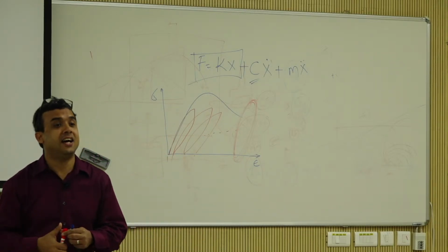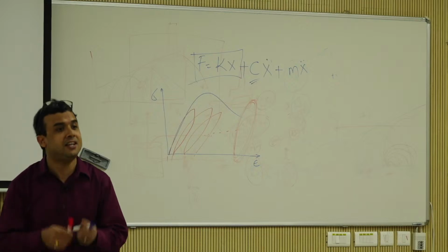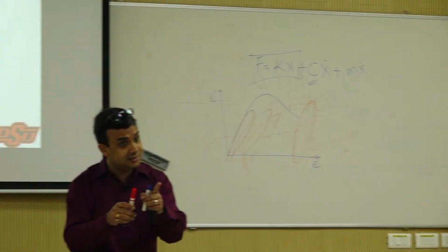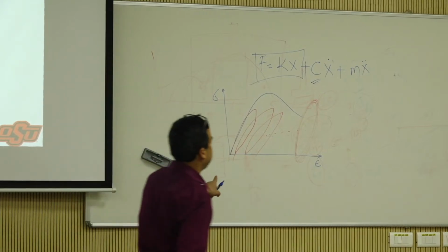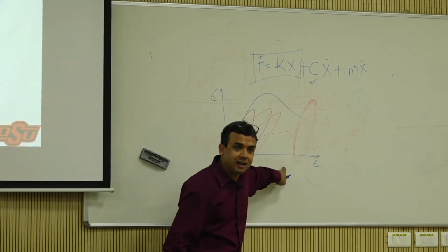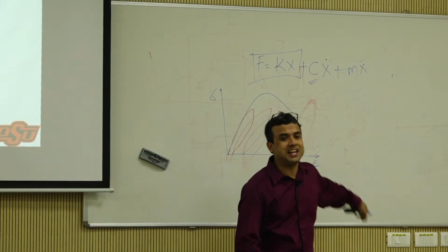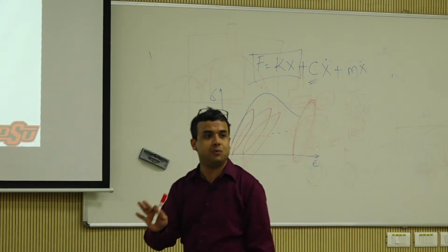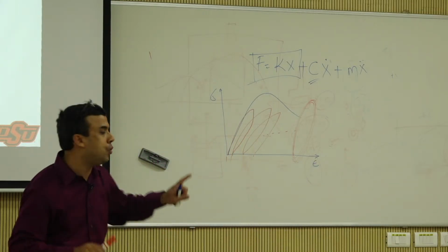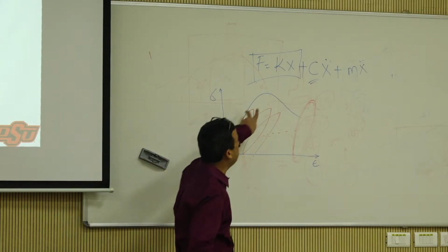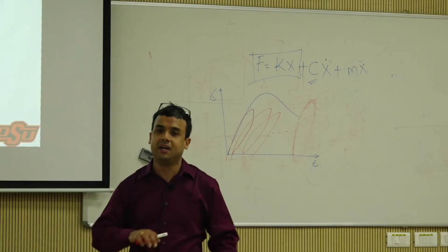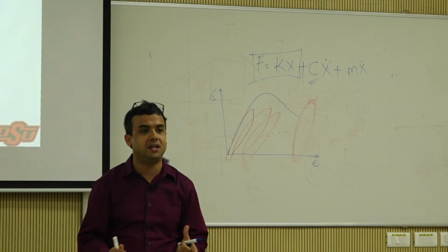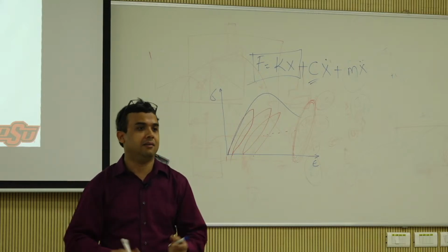So is resilient modulus an elastic modulus? Yes, but after a certain amount of plastic deformation has happened, and it is also something called a secant modulus, not an elastic modulus. We'll get into that. So why I showed you this is that all this behavior from now on, pretty much until the next 1.5 days, is going to be based on triaxial testing and triaxial behavior.